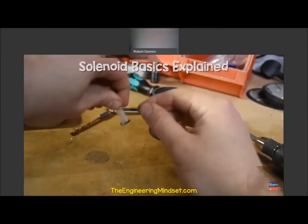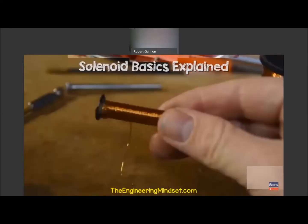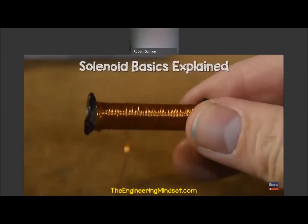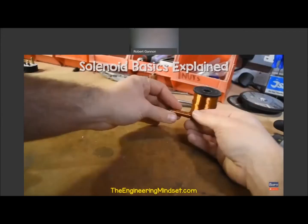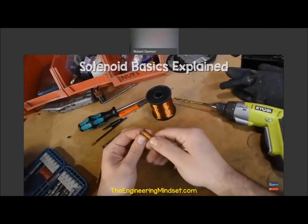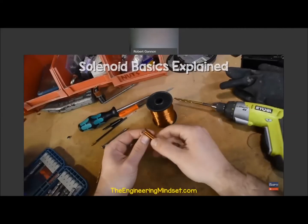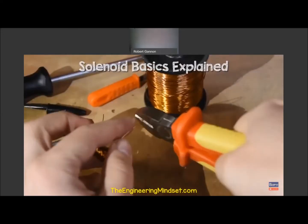So we simply want to wrap the copper wire as tight as possible from one end to the other. When we do that, we should end up with something like this. Then we need to wrap it a few more times in opposite directions to make it stronger. 3 or 4 wraps is probably fine. I didn't count the number of turns for this one as I'm just making a quick example for you. Once it's fully wrapped, we can just cut the wire and free it from the drum.